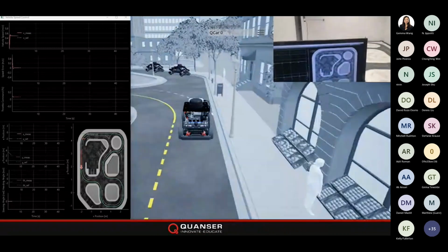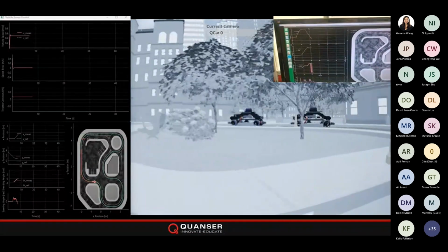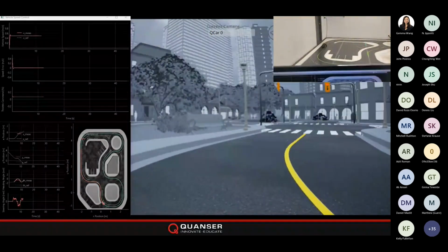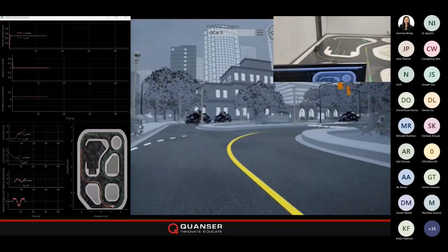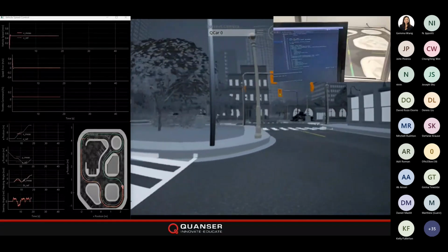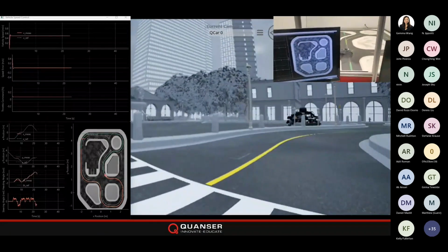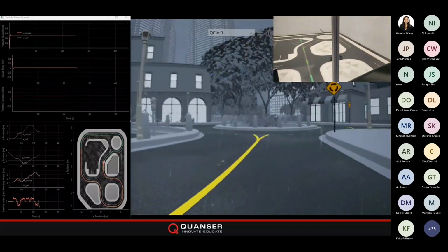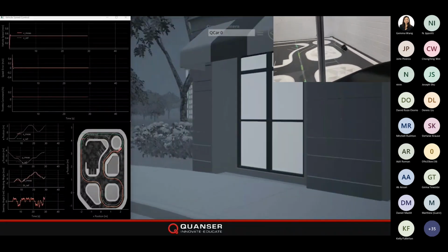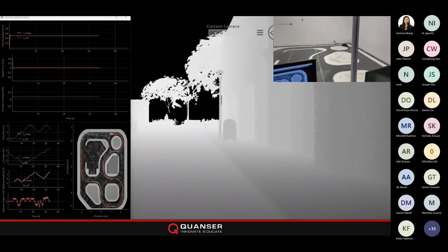The trajectory is completely up to you. We have a roadmap with the key points, so you can come up with your own trajectories as you like. But the point is designing the controllers and then being able to see how they perform, see how we can make them better, observing the things that happen like oscillation or instability. For speed control, it's based on a proportional integral control. And for steering, we use the nonlinear Stanley controller.